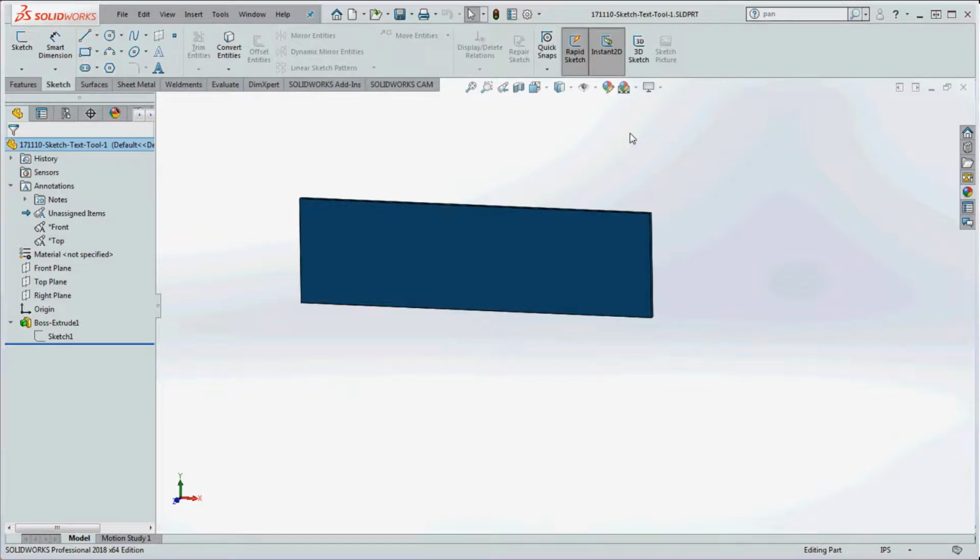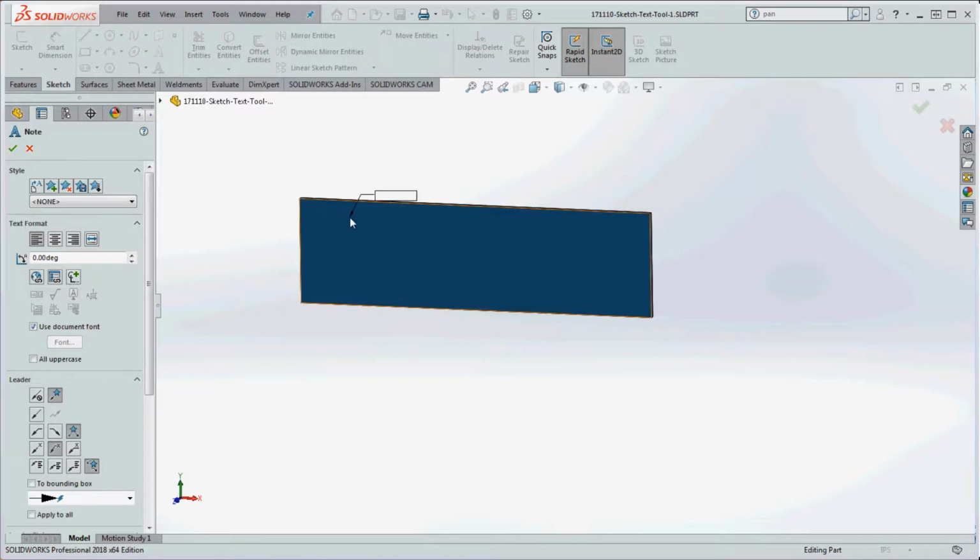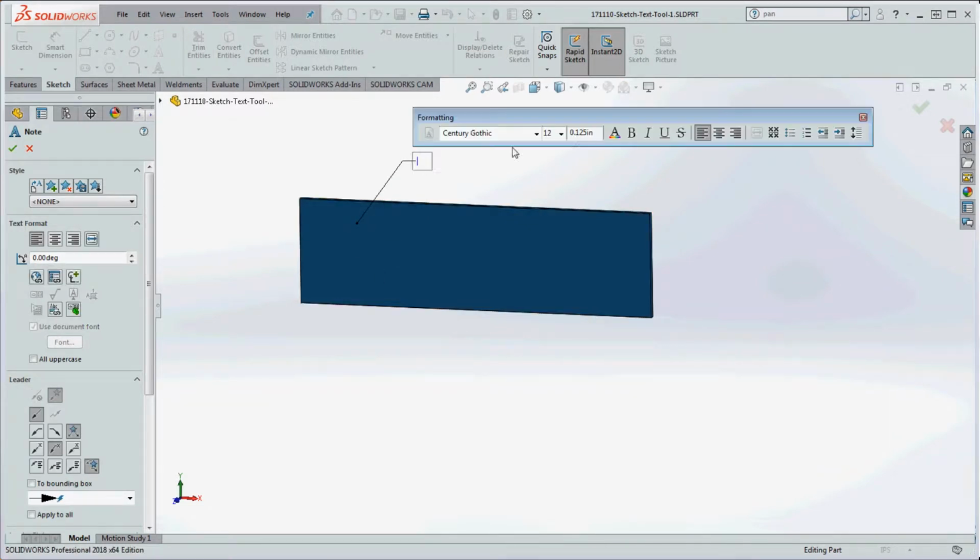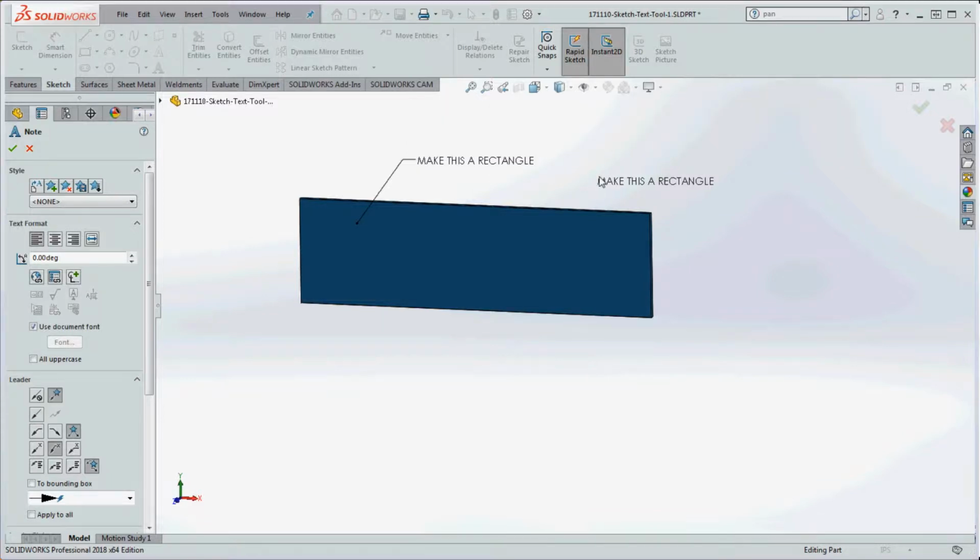When you put a note in here, it's going to be kind of like adding a note in SolidWorks, where you point to something with an arrow with a leader, and then you add some text next to that. It's very similar to what you might expect with a diameter or radius dimension, with a value derived from that when you use the Smart Dimension function. So very simply, if you just click on Note, and let's go ahead and choose this face over here and maybe drag that up, and see what happens.